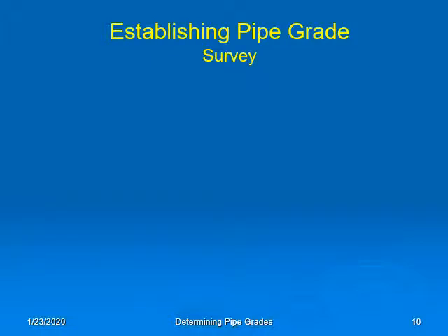In order to complete a subsurface drain or UGO design, we will need to survey the site. LiDAR data will be useful for planning, but a site survey will usually be required to establish design elevations to the hundredths of a foot.